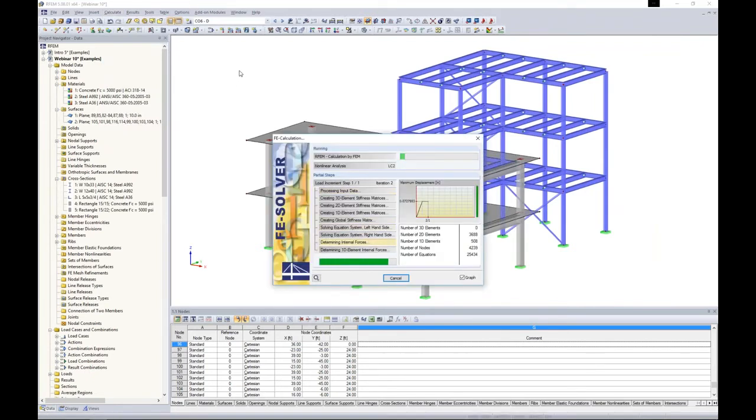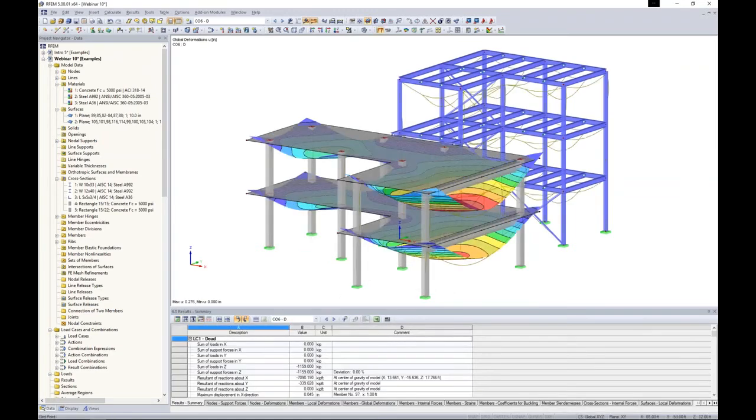So now the program is running through all of my different load cases, load combinations, and result combinations. It is doing a nonlinear analysis, and the reason why is because we want to take into account both big P-delta and little p-delta. We also get a little diagram here showing us our iterations versus our max displacement. If you notice that this is starting to just increase and increase and increase, then we probably have some type of instability within the program.